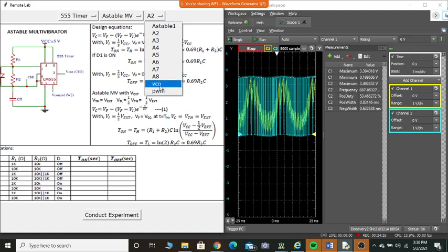But you can see the application of this triple pair timer as VCO or PWM in any of the 8 different combinations. These 8 different combinations correspond to different values of R1, R2, and the condition of the diode. For 4 different combinations, the diode is off. For the other 4, it is on. But unfortunately, now in my board, the diode is not switching on. You can see any of the 4 combinations. Correct?